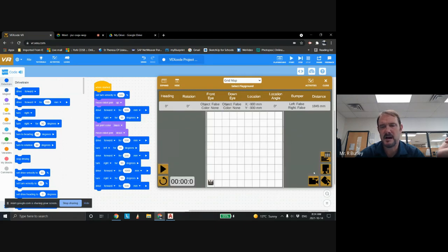I'm going to go back to the top view. And again, this is 1800 by 1800. When I draw it in AutoCAD, I'm not going to go quite 1800 wide. I'm going to go slightly narrower. And the reason I'm doing that is because when the robot comes to the end, if you send it to say 800 negative, it won't have the space to turn around. It'll hit against the wall. So in order to prevent that from happening, I'll send it negative 850 instead of 900. Just keep that 50 millimeter buffer.